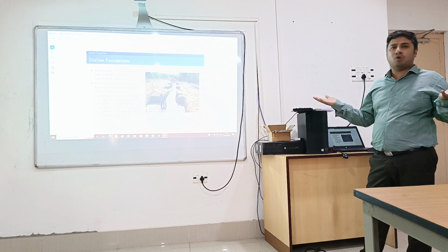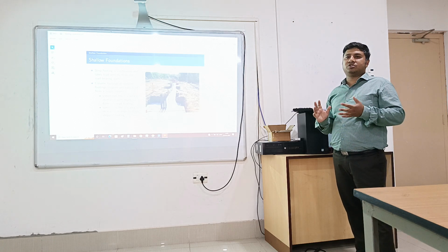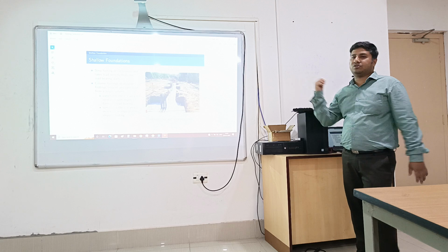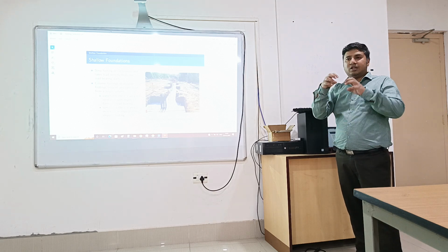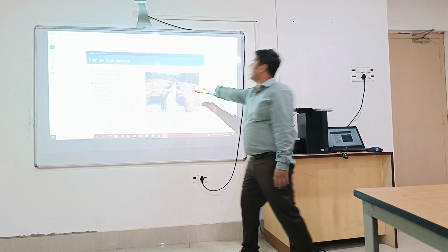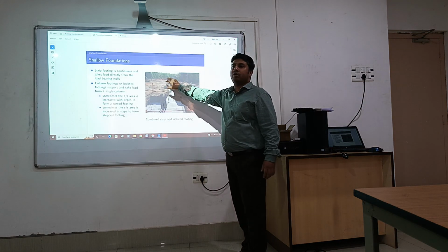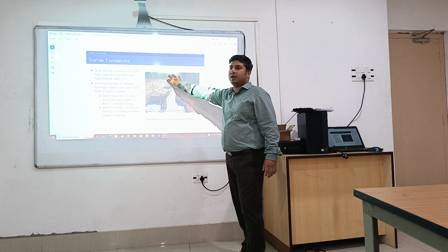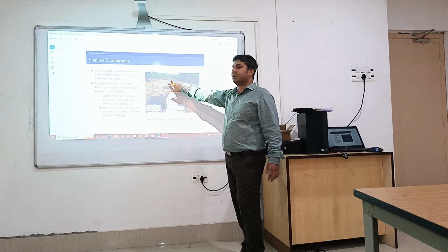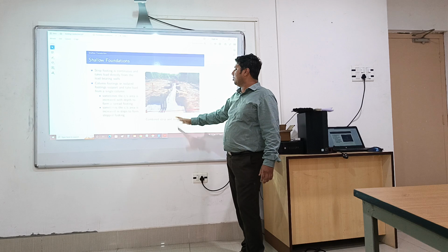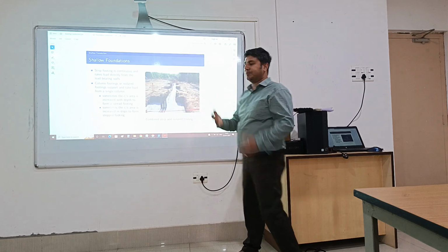If the soil strata all throughout is completely desirable for construction, then we will go for the isolated footing. Otherwise, the combined footing is more desirable if the soil strata compaction is not even throughout. If this portion is not compacted, or the soil in this part is different compared to this strata, and the hard strata is at a much better depth, then you may use the combined strip, which will resist your uneven settlement.